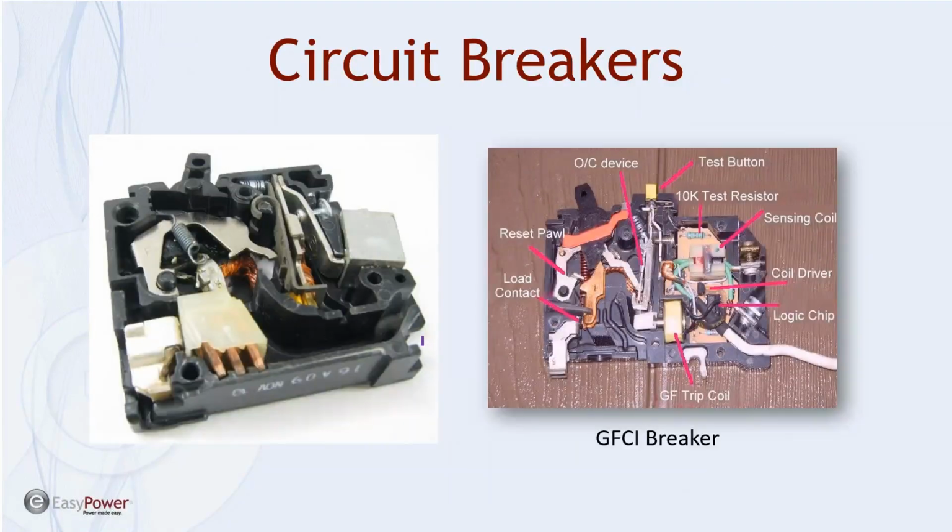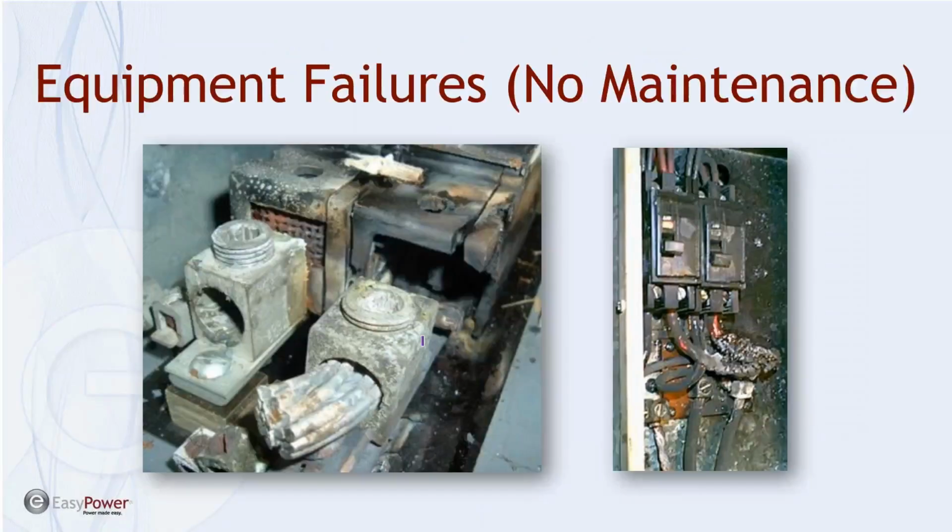Breakers, just to give you an idea of what's inside a breaker, there's a lot of moving parts inside of breakers, and if you never operate those, then there's some issues that you're going to come up with because the moving parts may not move the way that they're supposed to move. And so that's why these have to be operated from time to time. So this is, again, lack of maintenance.